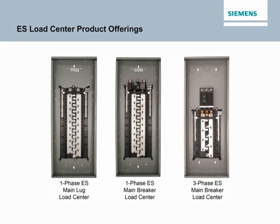The ES Series Load Center product line provides a wide array of variation to meet any application need. The following items summarize the range of capabilities: 1-phase or 3-phase mains, main breaker or main lug, 12 to 70 circuit spaces, indoor and outdoor enclosures, 100 to 225 amp current ratings, and also value packs, which are a mix of branch breakers provided with the load center.